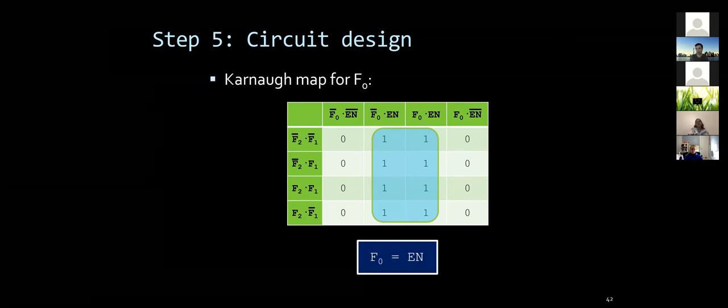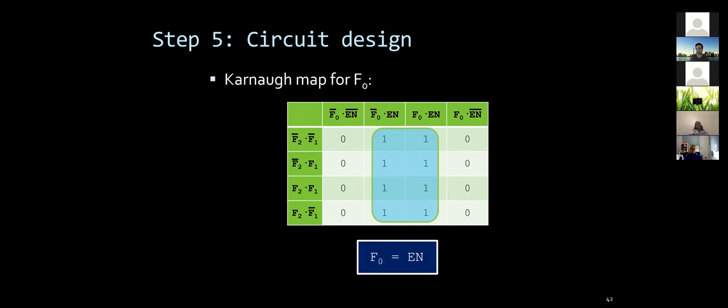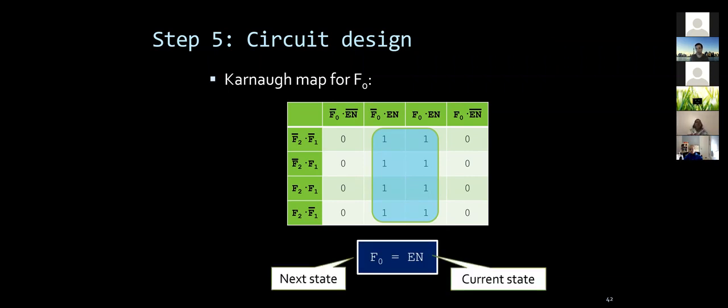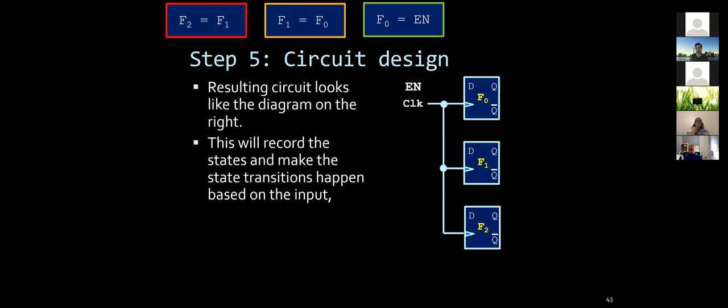So this is essentially the combinational circuits for our sequential circuit. We're almost there, but not fully there yet. So essentially what we got so far is the behavior of each individual input for each individual flip-flop. So these are our three flip-flops: flip-flop F0, flip-flop F1, and F2, right? These are D flip-flops, and those are their inputs. They are positively triggered, so the clock has to be negated. This is the clock, right? So we already figured out what outputs they generate.